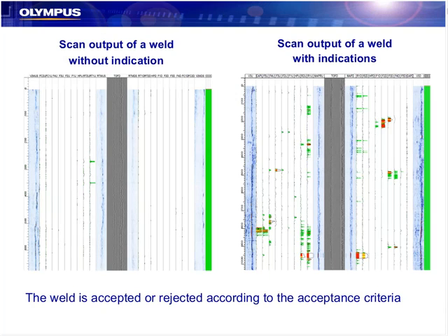So this might be what typical output would look like if we had a scan with no welds. Typically we use color coding and some other tricks so that we can look at a full volumetric scan 360 degrees around the weld and immediately key in on areas that might need investigation or sizing. We'll look at those color codes so they make a little more sense, but here you can see this one. We got some reds and yellows, some other things that are going to bring our attention to those defects to do further analysis.